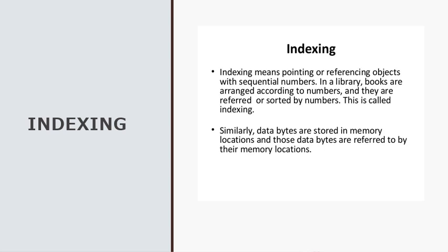For example, a list of numbers is stored in sequential memory locations. To access this list, we need the address of the first element and the total number of elements in the list. We can use a register pair as an index by loading this address into the pair and then incrementing it to access each element of the list.